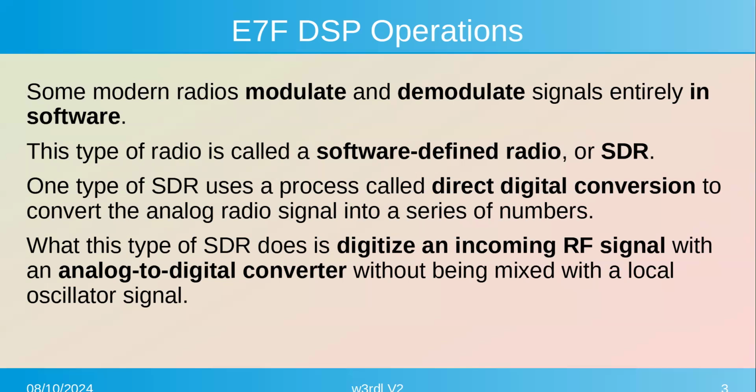There may be some analog circuitry there to change the frequency so they don't have to use as expensive analog to digital converters, because that's really the secret. You need a very high frequency A to D with a lot of bits, and those aren't cheap.